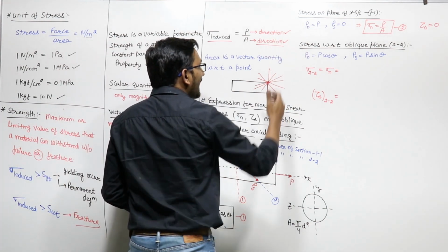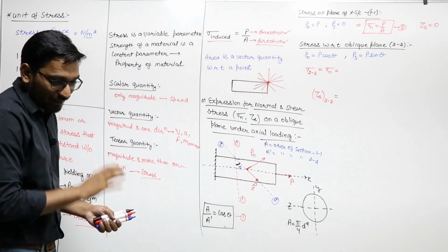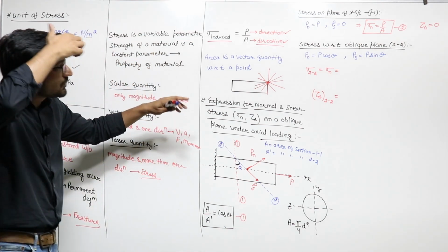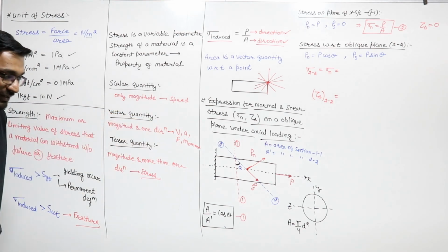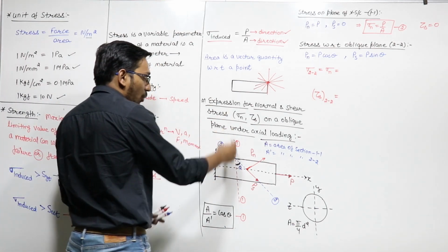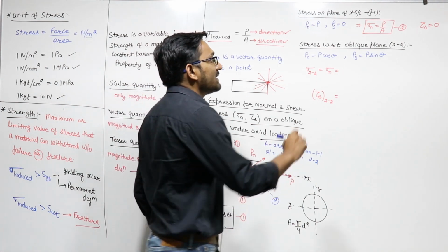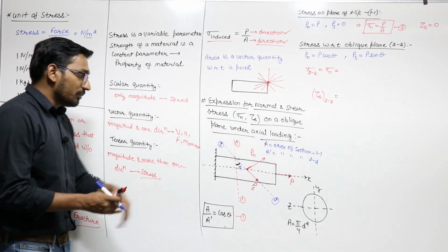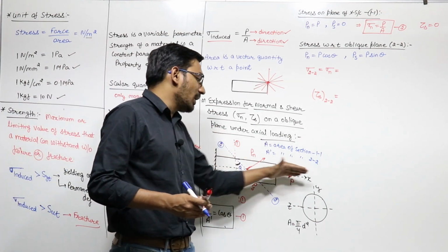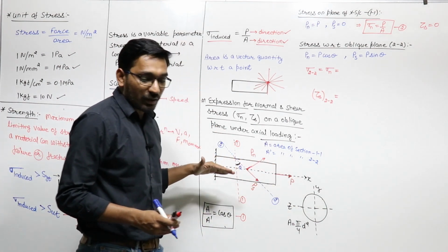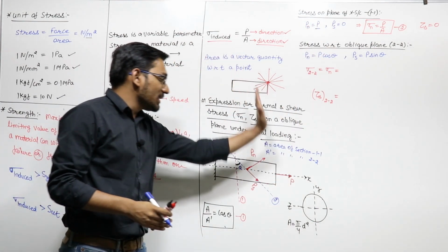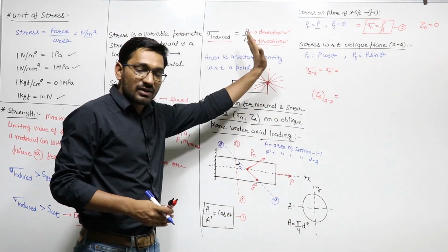your theta in this case, so if I can write here one thing, what are the stresses on the plane of cross section? This is the plane of cross section 1 1. On the plane of cross section, the normal load, which is perpendicular to the cross section, is P, and the shear load, which is parallel to the cross section, is 0.